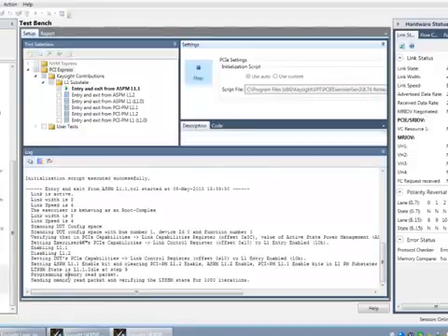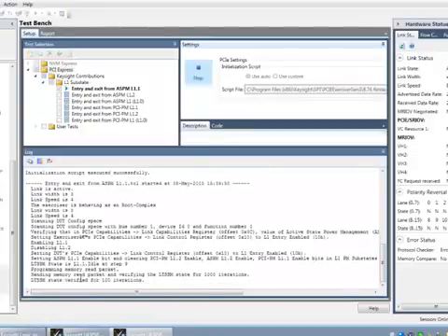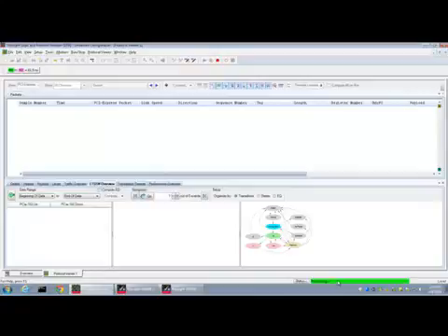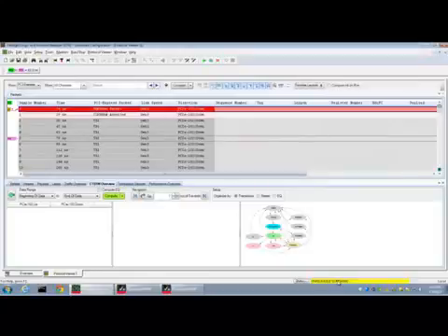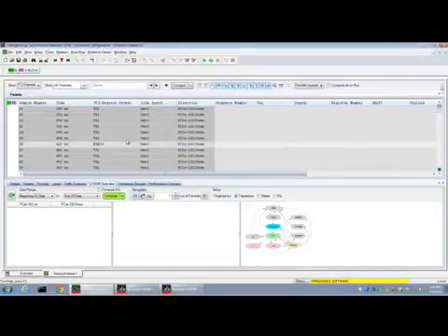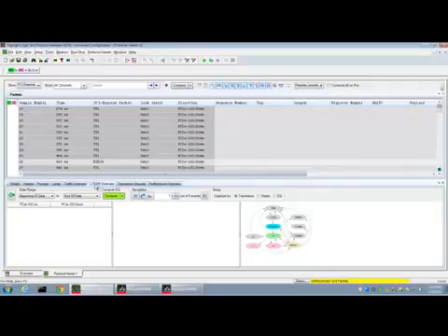So it begins running this test over and over again of entering the LTSSM state. I bring up my analyzer, do a data capture. Capture, processing, and as soon as it fills the buffer, it will stop and show me exactly what occurred across this link. So in my trace I see a clock request, I see the recovery signals of the data going across the link.